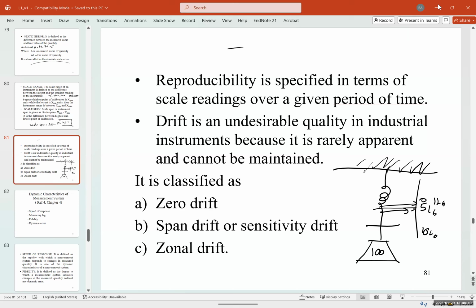Meaning when you test 4 or 5 blood samples, it creates a little bit of drift because the sensor itself becomes a little bit contaminated, or you have electric pulses, and a lot of different problems cause drift. The way that we could fix these drifts is to recalibrate. So if you forget to recalibrate these devices, it will show measurements that are not true, inaccurate.